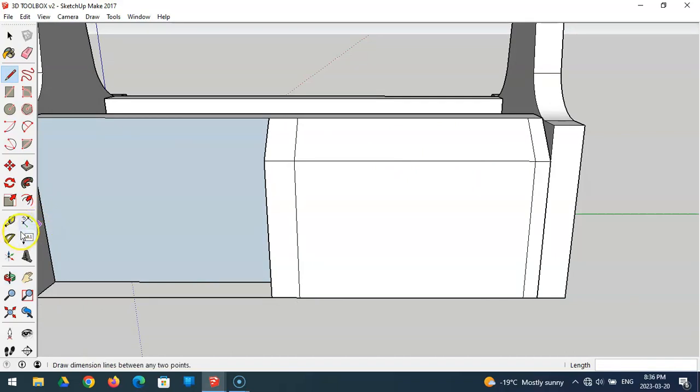Now what I need to do here is space these out. I want them evenly spaced. So I have 160, so I'll just put that measurement there for now. I want one more here and one more here, so that leaves me three spaces in between. If I have two that are 20, that's 40, and I have 160. 160 minus 40 is 120, divided by 3 is 40. So there should be 40 millimeters in between each one.